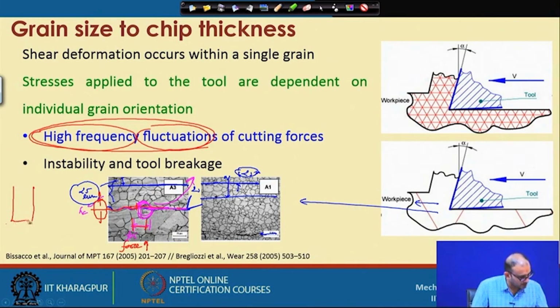So this is our end mill cutter, and consider this diameter to be 200 micron. Now when the tool diameter is very small, the effective cutting length is also very small, because you cannot have a very long overhang on this part. And now when you are cutting this part, consider it is moving in this direction, and you are getting one particular boundary here.